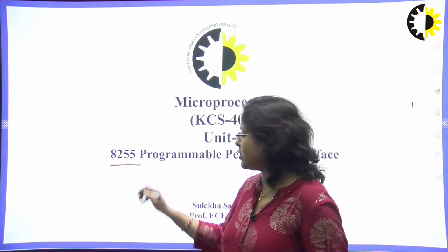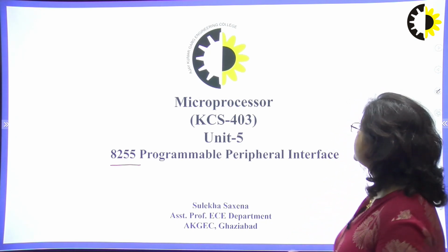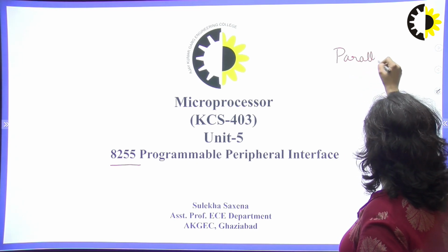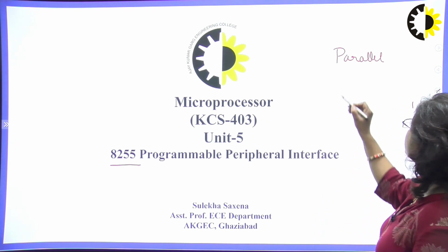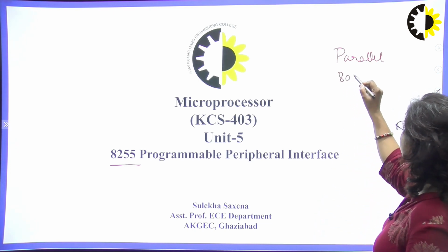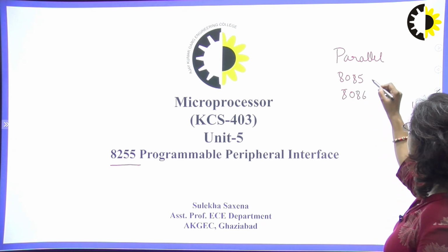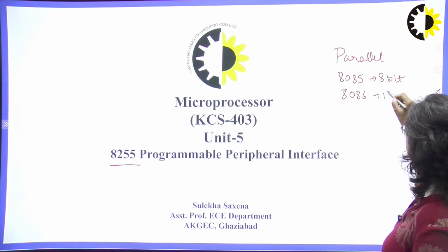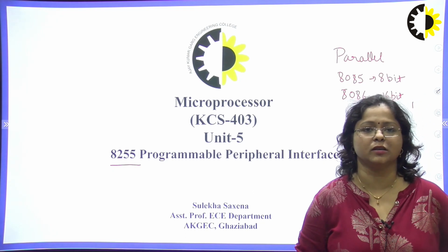As we all know, for any microprocessor the data normally travels in parallel mode. Microprocessor normally communicates in parallel. That is, if a microprocessor is 8-bit like 8085 or 16-bit like 8086, the complete 8-bit or 16-bit data is read or written at a time in a single machine cycle.